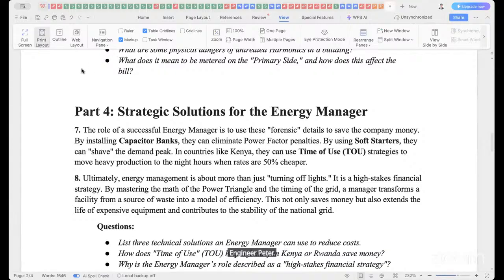Good afternoon, everybody. In a system like the one you just described, ideally the first thing is to find a way to synchronize all your energy sources, be it grid or off grid. When that is synchronized, you make use of a smart changeover switch, as the first contributor said.